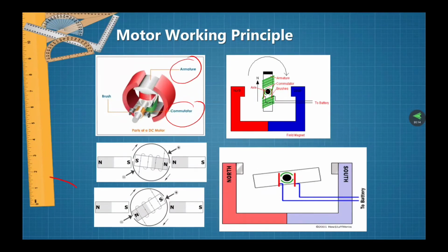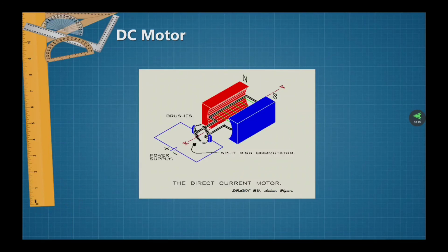When the armature windings connect to the DC supply, an electric current is set up in the winding. Then permanent magnets or field winding electromagnetism provides the magnetic field. In this case, current carrying armature conductors experience a force due to the magnetic field, according to the Fleming left-hand rule. The commutator is made segmented to achieve a unidirectional torque.